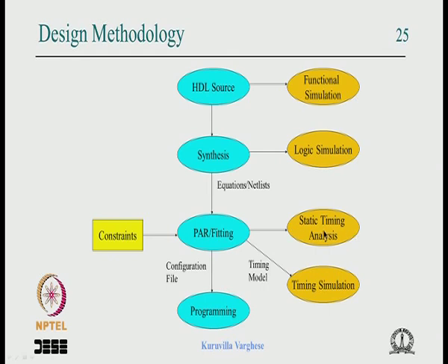There could be another situation where there is a source register and a destination register. The destination is not clocked on every clock; the source gets input data but the result gets latched after 2 clock cycles, enabled through the enable of the destination register by a state machine or a controller, which the timing analysis tool has no way to know.